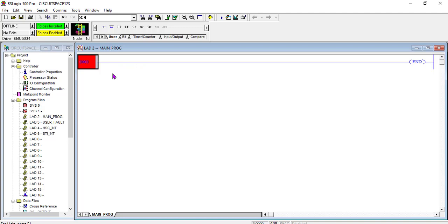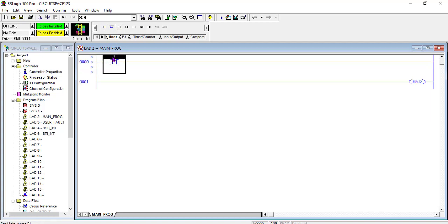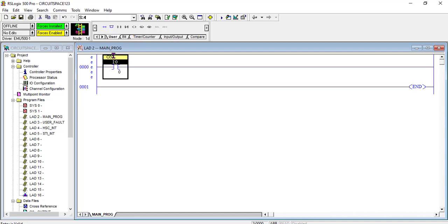Now, this environment as usual. For start programming, I want to deal with latching. First thing, I add a rung, then I add a contact. My contacts, I'm still using the same thing I'm used to. You always see the name appearing because the name is already registered in this very project. If I say on, I need an output, but the output I want has to hold when I release my hand from the button. That means I must latch it, but you can latch in many ways. So let me show you how I can latch.